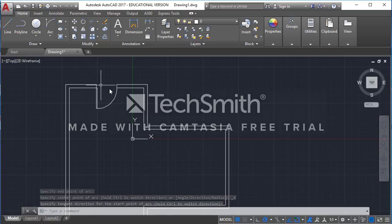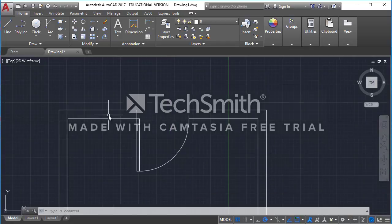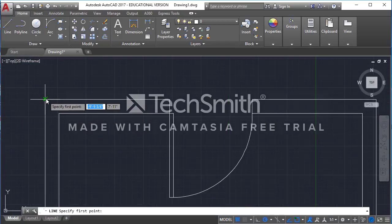All right, so let's do a couple more things. We'll learn just a few more commands before we take our break and turn you guys loose. Let's go ahead and create a window. So what I'm going to do is click on my line tool or type in L. Notice that when I bring my mouse over to this endpoint, I'm getting this little green line right here. As I move my cursor along the edge of that wall, it's telling me that when I click my mouse, I'm going to be on that wall.